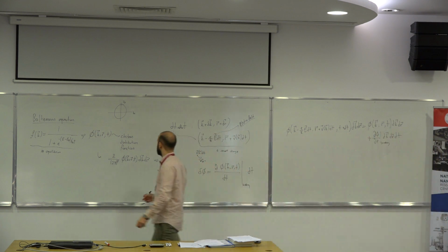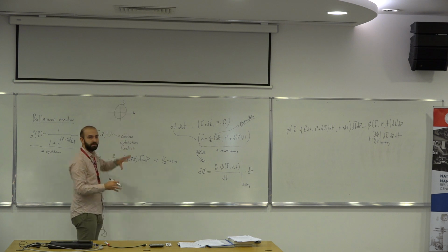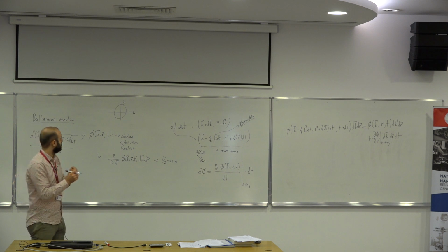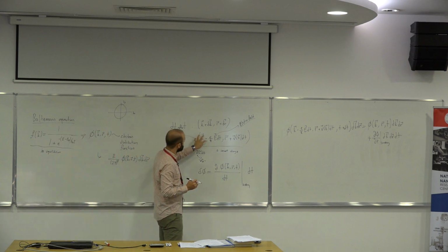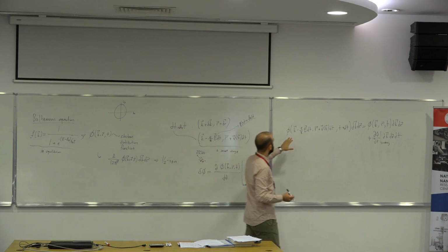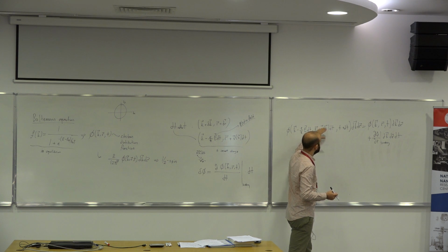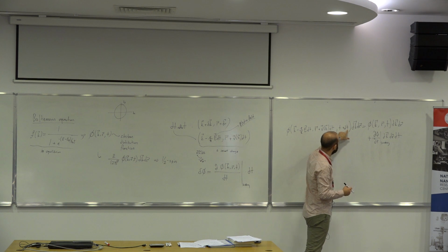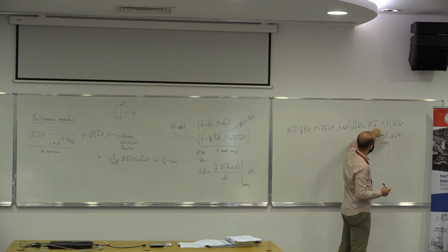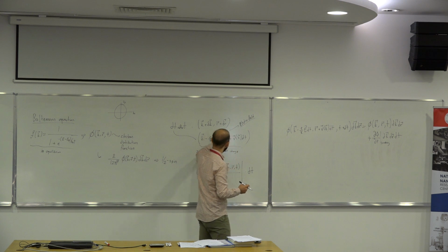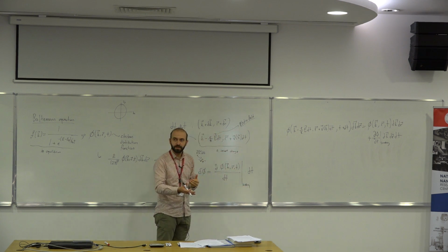I have a distribution function that defines how my electrons fill each individual energy state. Then I look at a very small change within this distribution, and I write that small change in terms of time delta t after delta t, the initial starting distribution function, plus the change that's caused by the scattering event because of the external force.